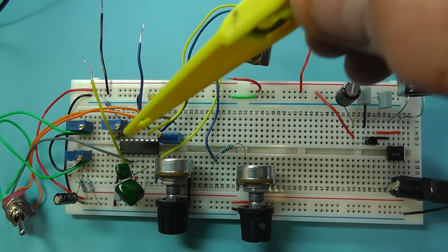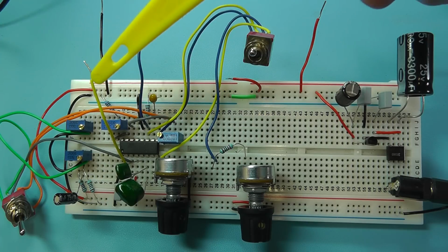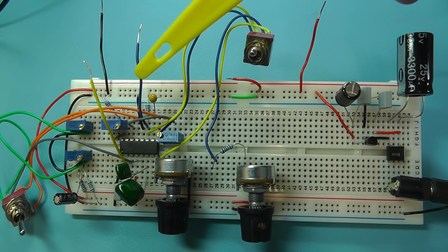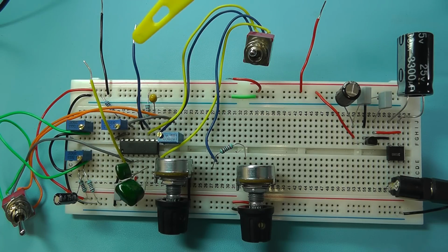The output from the chip is coming from pins 2 and 11. On pin 2 we get the normal sine wave and triangular waveform coming out, and on pin 11 we have the square wave and the pulse waveform coming out. When we switch to pulse mode, we can also get a form of ramp waveform coming out of the normal sine wave output here at pin 2.